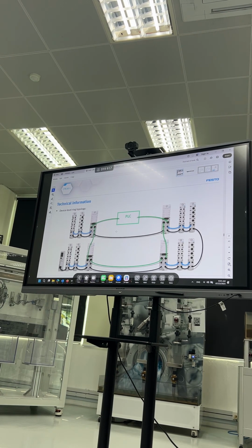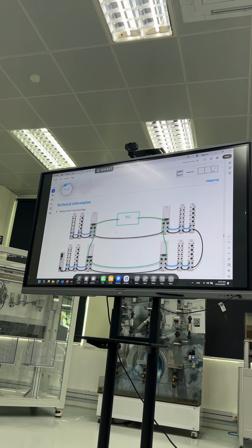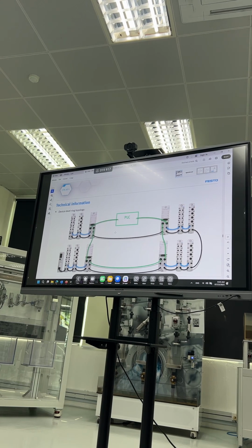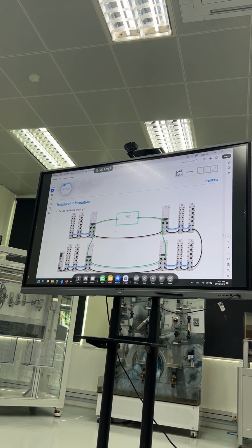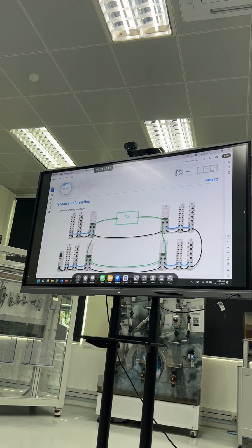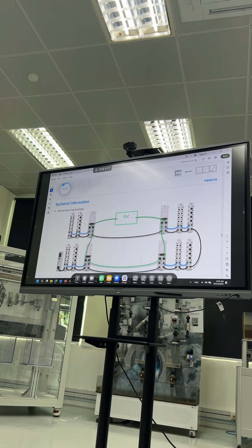Okay, for EtherCAT, I'm not sure. Tom, from your experience, have you heard of EtherCAT in a ring loop, or redundant, or Beckhoff? To be honest, I do not have information on whether our EtherCAT module can support redundancy from a Beckhoff PLC or not. But from what I know, Profinet and EtherNet/IP, we can support the ring loop. For EtherCAT, I'm not sure.